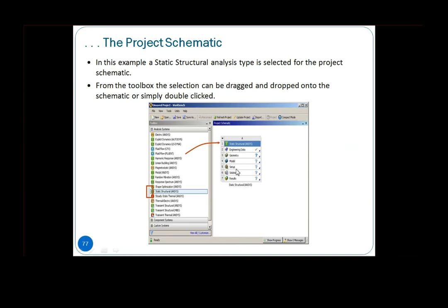Then the setup here, when I say this setup, it's before you start performing this analysis or finite element analysis. The setup that I have mentioned to you, you need to have the dimensions, which is the model itself. You need to have the correct material properties that you have to assign to all these models. Okay, you need to have the connections, or what we call how they are being bonded, or how they are being connected.